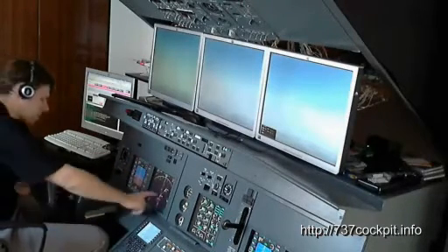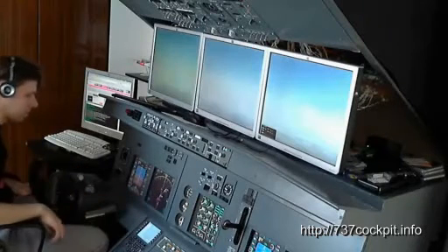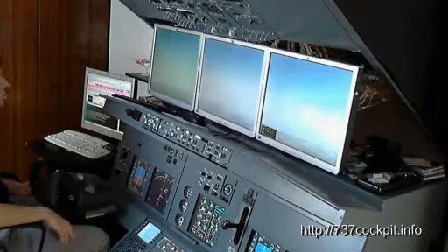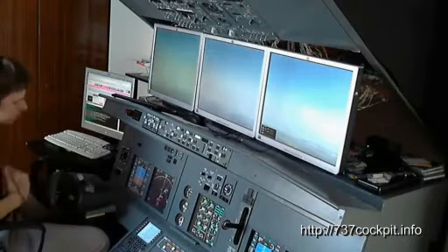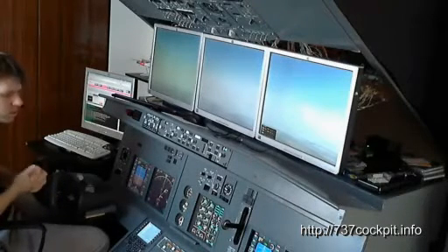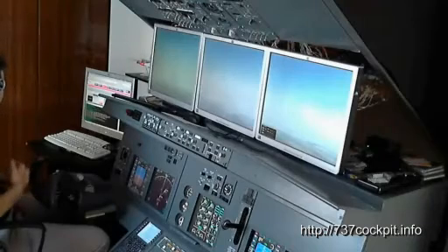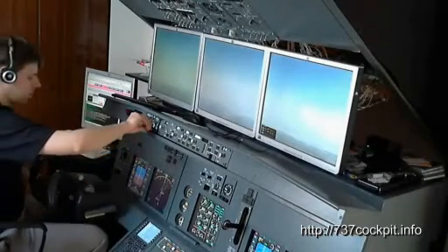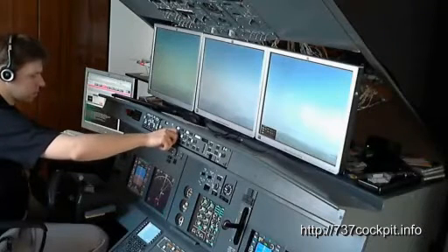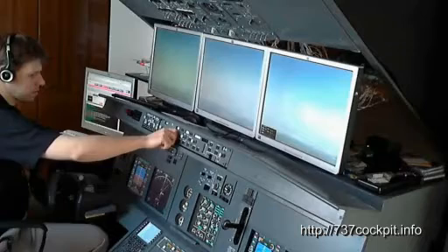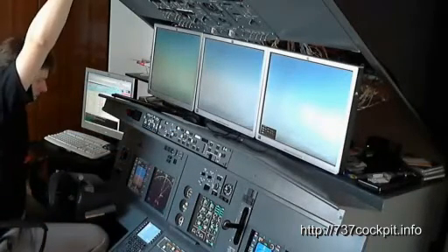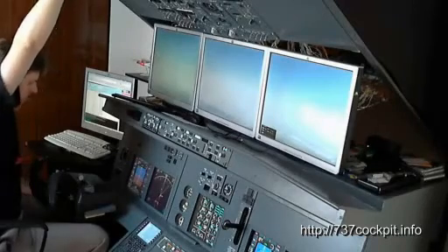until we are reaching our localizer and make then a cut to the localizer and glide slope. When we are establishing the localizer with glide slope, we will contact the center again and we will get then the landing clearance. We can now start configuring our aircraft and start slowing back to 180 knots. Wind 130 going 10, runway 16 takeoff intersection 34.